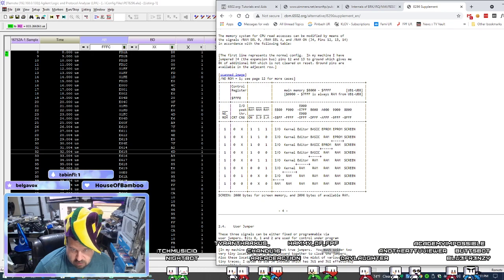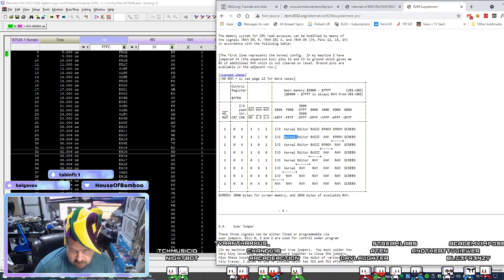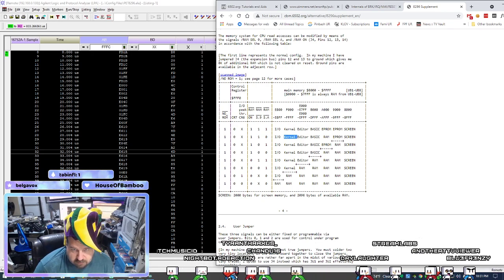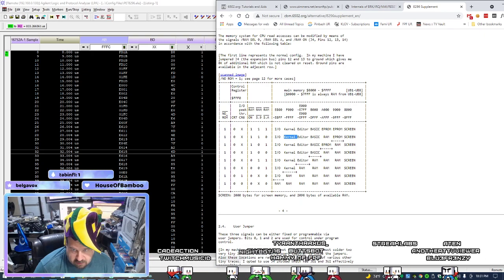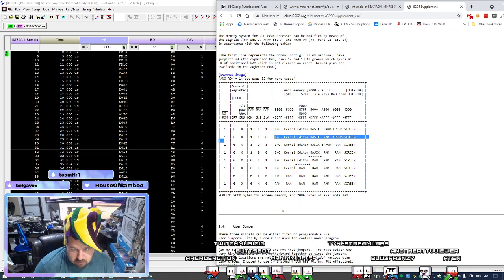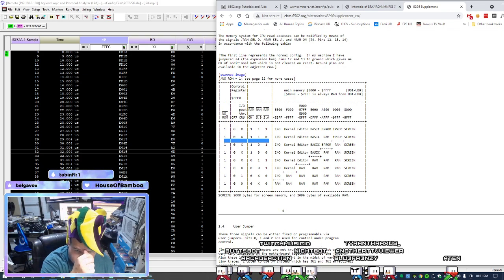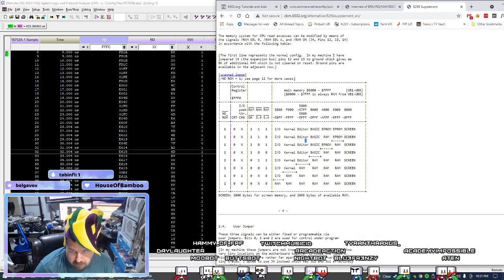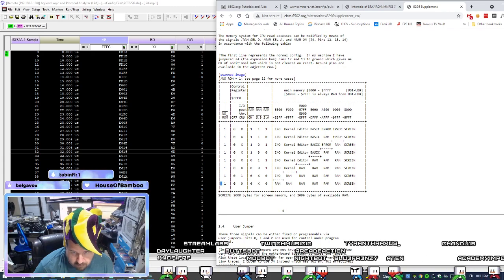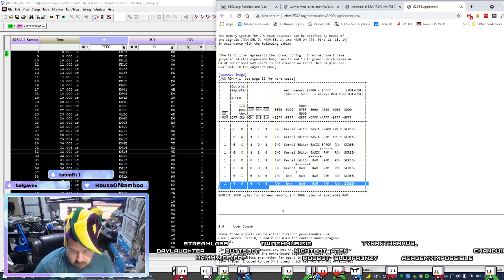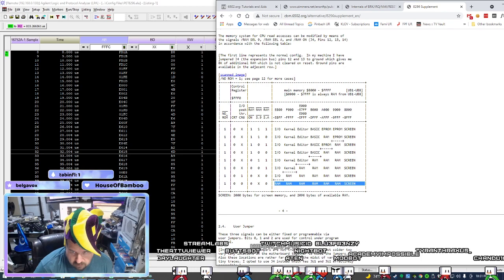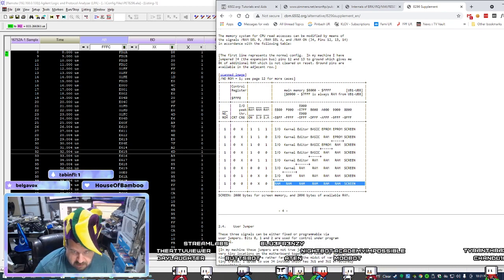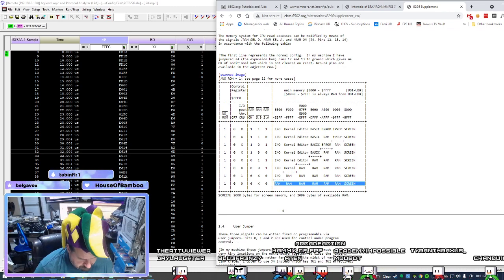So you can take the kernel out of the equation. Like if you wrote this value here to the control register right here, you would basically go to this mode. But if you wrote this, everything would be RAM, and you wouldn't have access to any of the ROMs again.